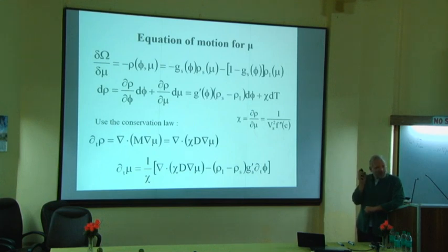So remember, the pure substance solidification was driven by the transport of heat, and heat diffusion is about of the same magnitude in the solid and the liquid, meaning the heat diffusion coefficients in solid and liquid are often of a comparable order of magnitude.